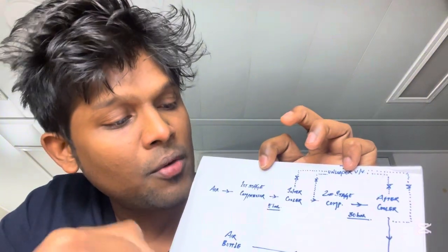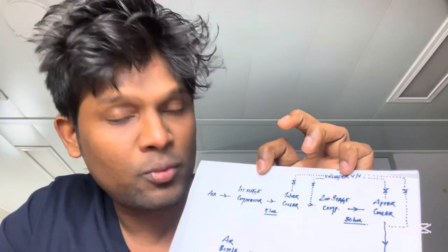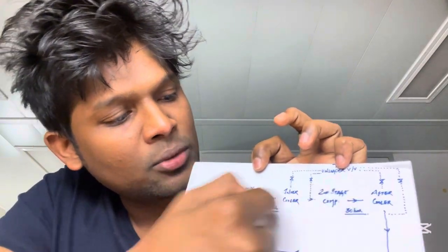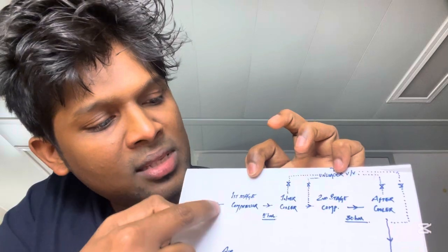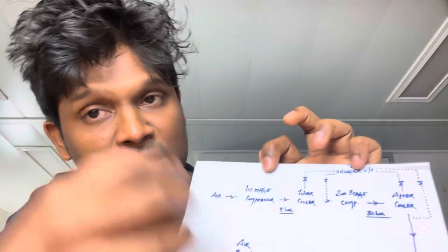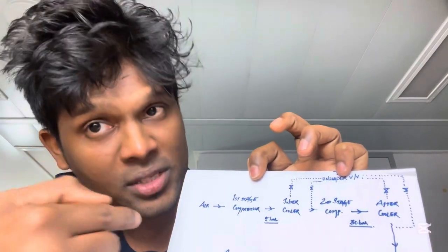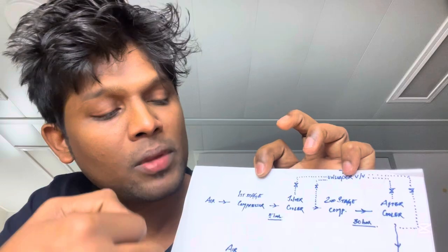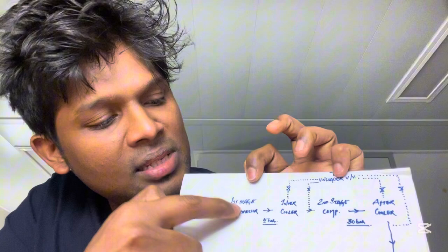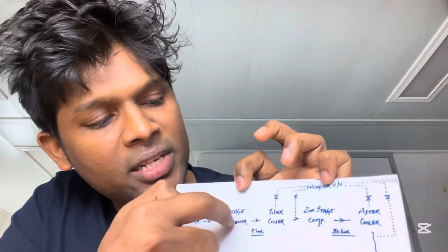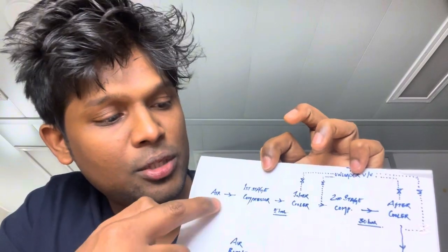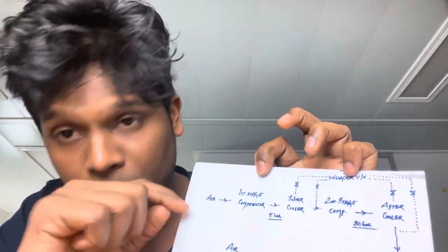Now, when we are starting the air compressor, since this is a line, all the way the air will be passing through this, and since all of this is pressurized, initially 5 bar, then 30 bar, this line will be holding air till it reaches the bottle. So when you start an air compressor, when the sucked air is compressed and pushed from this line to that line, some air is already present inside the line. This air will act as a resistance to the newly sucked air.